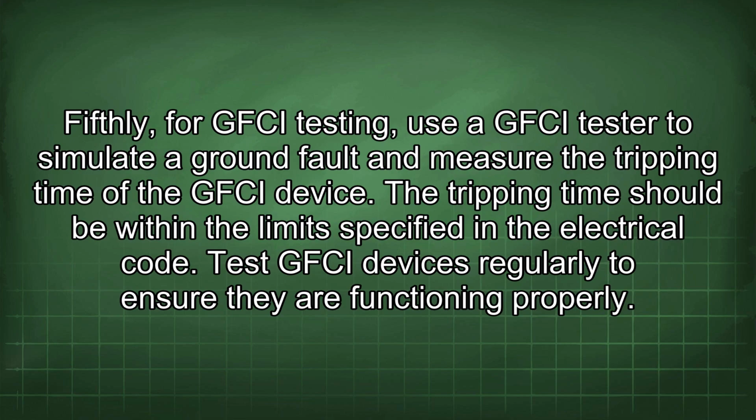Fifthly, for GFCI testing, use a GFCI tester to simulate a ground fault and measure the tripping time of the GFCI device. The tripping time should be within the limits specified in the electrical code. Test GFCI devices regularly to ensure they are functioning properly.